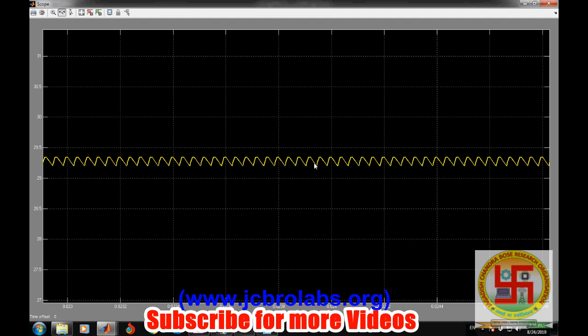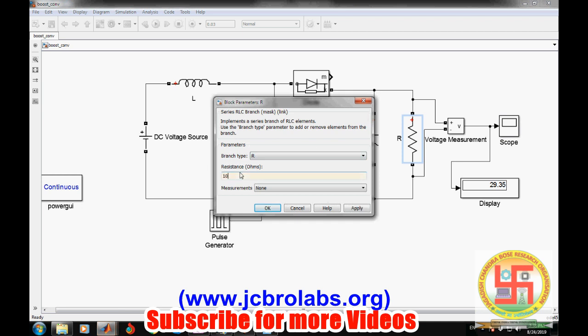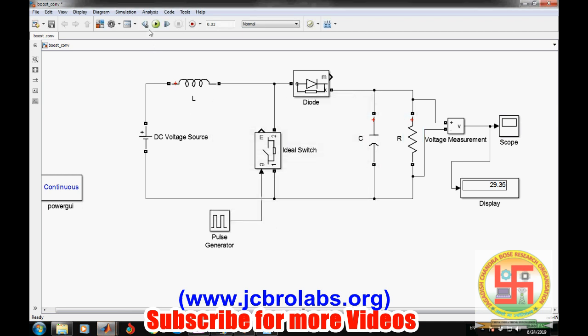Now let's change the value of L, or let's change R first, and then see what happens to the output voltage. If we increase the resistance R, you will find it is no longer the same value of 30 volt. So there is a limitation over R, because L is determined by R. If R is changed, L has to be changed, or you can think of it vice versa. If L is fixed, that means this fixed value of L puts some restriction on the allowable range of this load resistance. Okay, so let's try to change this R to 10 ohm.